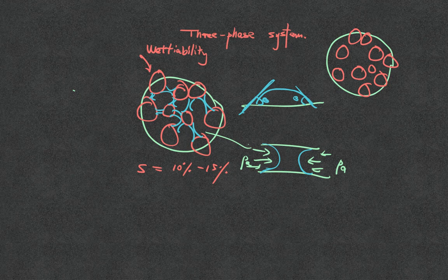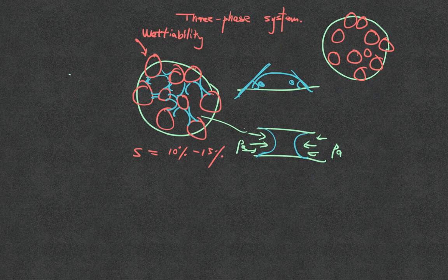The sand itself has weight, right? I can actually use the water to support it. So the water affects the material behavior. In this particular case, where the water forms patches, we call it the capillary regime.